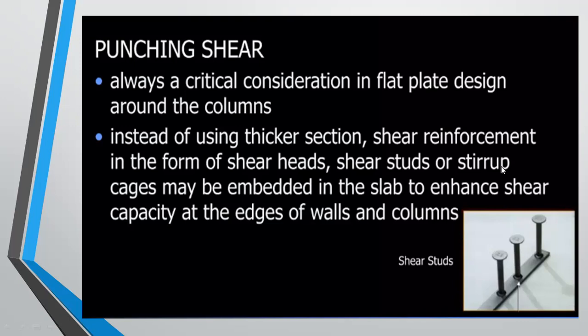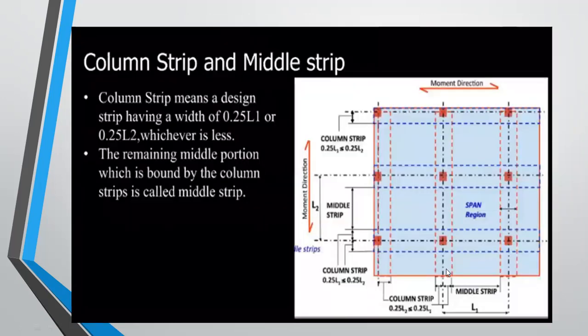Okay, in general, to counteract shear stress, we provide stirrups. In flat slab, to avoid punching shear, we provide shear reinforcement in the form of shear head, shear stud or stirrups. So in the picture, you can see that shear studs are used.